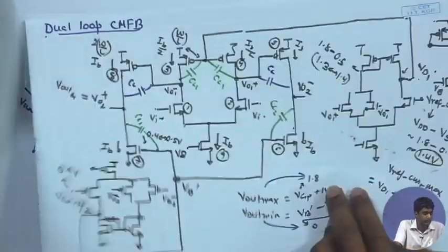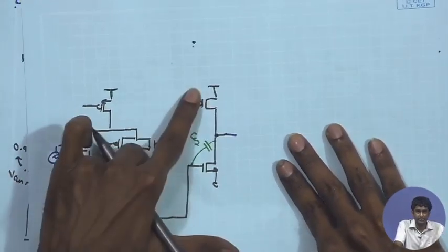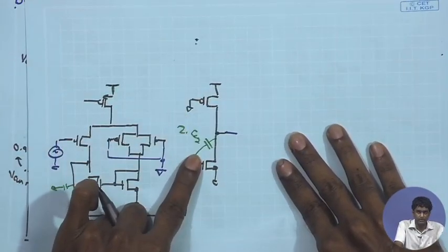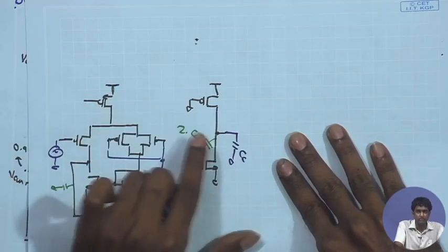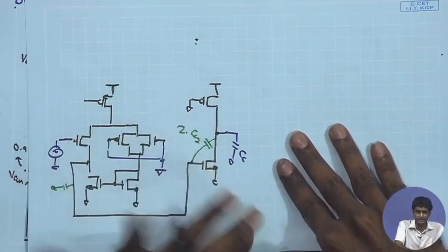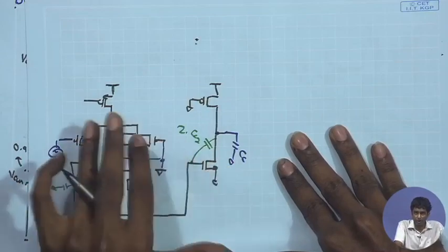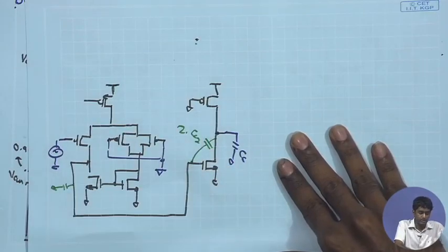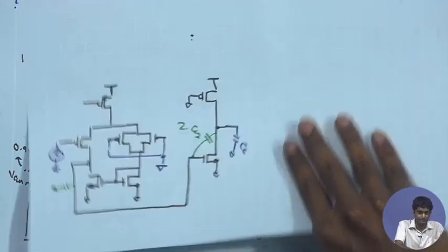So, if we recall our common mode half circuit of the second stage, here you will have CC appearing between this point and ground, it will not have any multiplication as such. So, again CC is not significantly interfering with the compensation of my second common mode feedback loop, it is just appearing as an additional load capacitance over here.